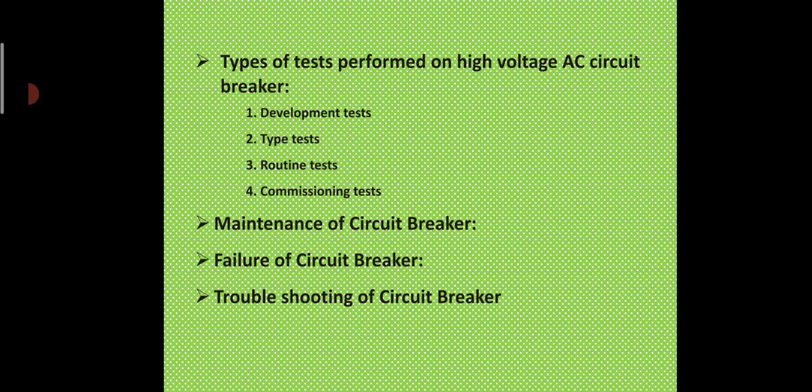Now, failure of circuit breaker. The possibility of failure of equipment is less when regular maintenance is carried out but cannot be neglected. Similarly, in circuit breaker, regular maintenance of mechanism, insulation, and switching medium is carried out regularly even though it sometimes fails to operate. Causes of failure of circuit breaker: failure of operating mechanism, failure of dielectric, dirty quenching medium, contacts thoroughly burnt, internal flashover, leakage of the quenching medium, loss of components, a sluggish contact travel, and high value of transient recovery voltage.